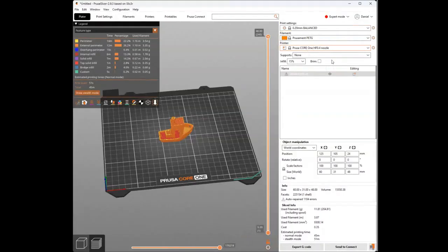One of the things you'll notice is that they have different nozzle sizes. So this is a 0.6 millimeter nozzle size, and this is a 0.4, the new machines that are coming in. 0.4 is a smaller hole, so it's finer, and it's able to capture more detail, but that also means it takes more time. It still takes about the same amount of material, so the cost doesn't change, but the time does increase. So you have different settings.